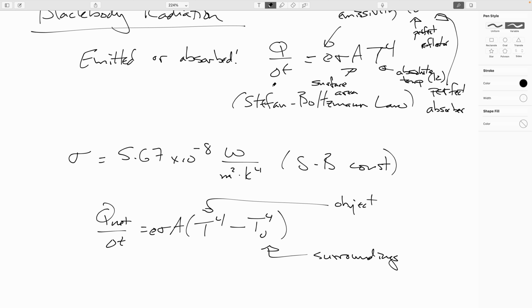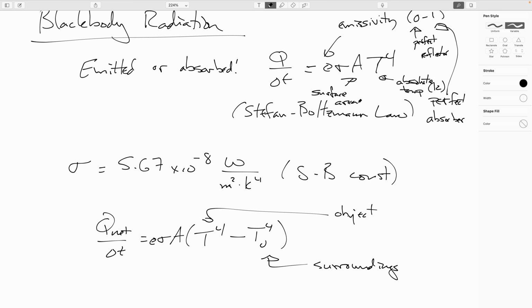By the same token, this is also done in a lot of cars, especially cars that have glass roofs. They actually have very cleverly chosen layers of material that, although the object looks clear, in the infrared, where most of this transfer is happening, the emissivity turns out to be a bit of a train wreck. And so the car doesn't do a very good job of emitting or absorbing heat. So in the summer, the light shining in from the sun isn't baking the car. And in the winter, when the heat is trying to escape the car, it's also doing a bad job of radiating it out to the environment.